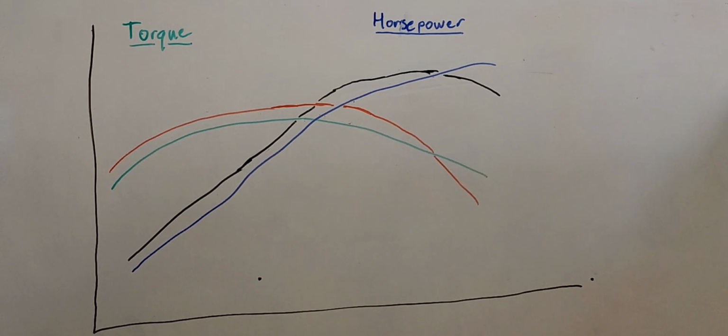Looking at the addition of the red and the black line, we notice a distinct trend as to how the engine now performs. Over the first 3/4 of the RPM range, the brake mean effective pressure on the red line will be higher, and this is also attributed to what people call volumetric efficiency.